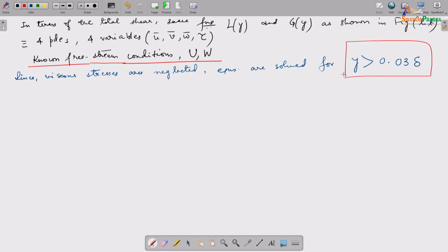But then we have to consider that. I can't just neglect the viscous sublayer. Essentially we use the law of the wall to extrapolate data into it, because we need the wall shear stress, then we will calculate the drag. Otherwise, what is the point of solving all these things? That is the major part when you are considering the boundary layer. One of the primary reasons for studying the boundary layer is to know what the drag will be like.